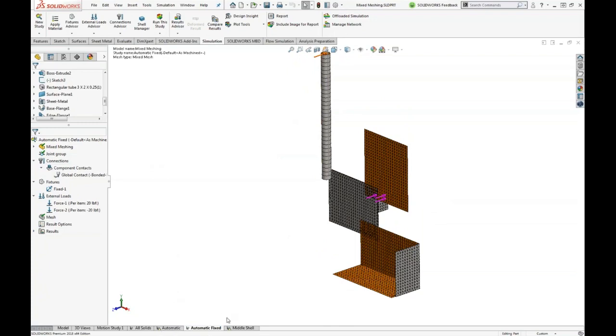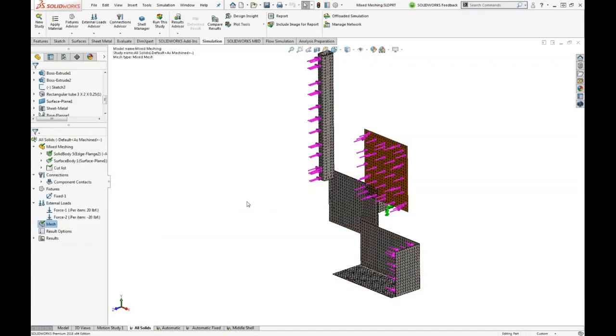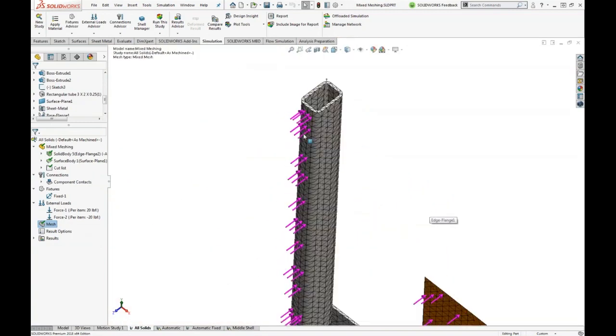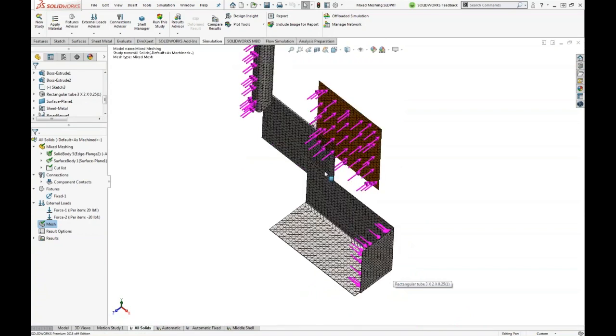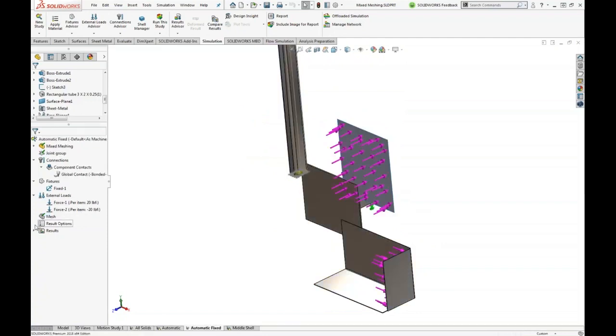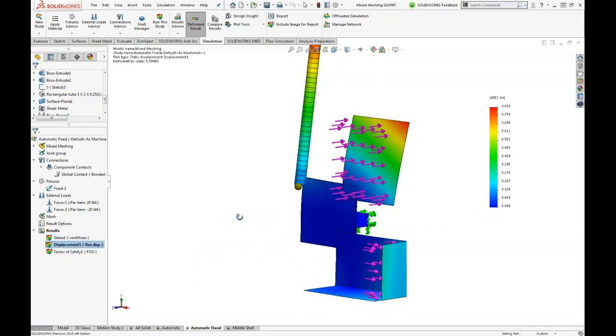But why do we take advantage of things like shell and beam mesh? It's because they are more efficient, right? If I was to mesh this Frankenstein geometry with all solids, so everything is meshed to its true shape, I've got a mesh element across the thickness. It's highly distorted, so it's probably not a very good result. Same goes for this guy. It works out to roughly twice the elements than if I use shells and beams, which is what I've got here.